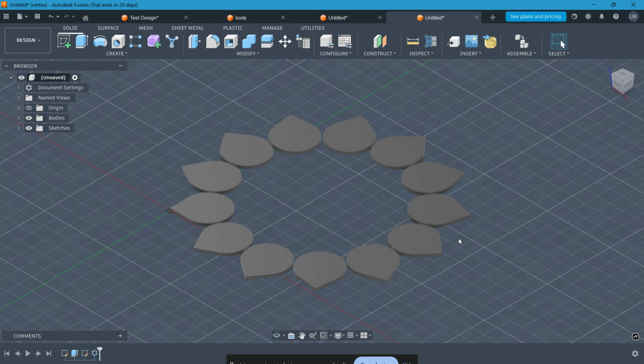It is always a good practice to try re-importing that file back into your software or a free viewer, just to verify that all parts of the assembly were captured correctly. This simple verification step can save you a lot of headache down the line when working with external manufacturers. And that is really all there is to it. You have effectively mastered the standard workflow for exporting high-quality engineering data.